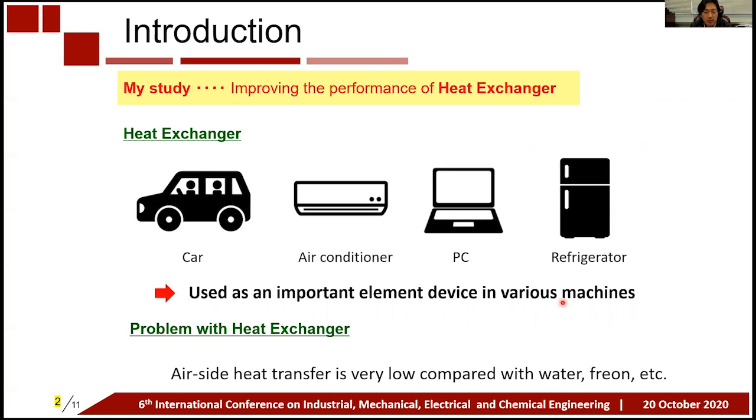But the main problem in the efficiency of the heat exchanger is that the heat transfer coefficient on the air side is poor. So it is necessary to increase the heat transfer area. As a result, the heat exchanger must be increased in size.